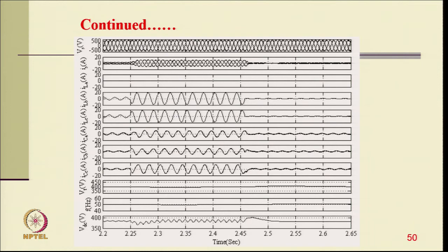And these are typically the case study with a kind of load. You have a single phase, a line to line load, single phase load, and these are the generator currents. You are having almost a very light load here, but you can see the generator currents are balanced, sinusoidal and at unity power factor, and this of course is the DC link voltage. So, the compensator is providing all the compensation for this, and the terminal voltage is also regulated, and frequency is also regulated.